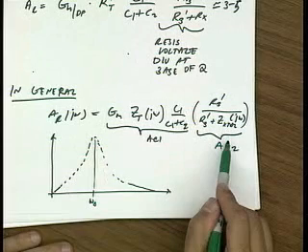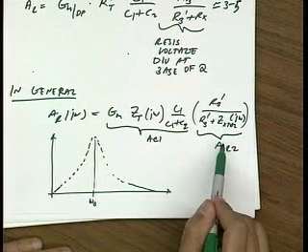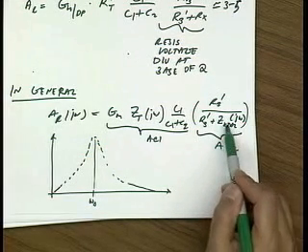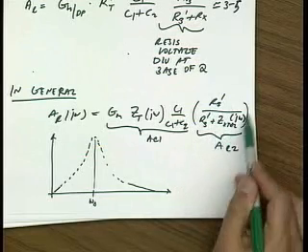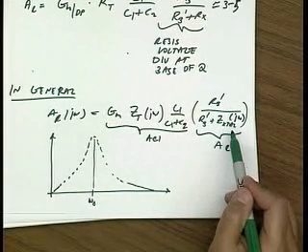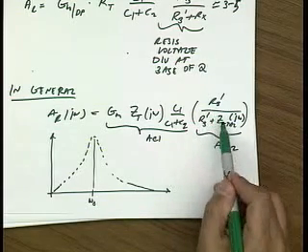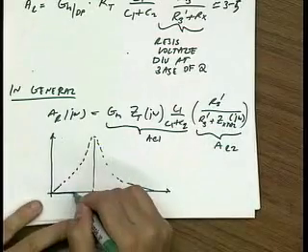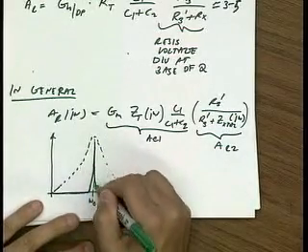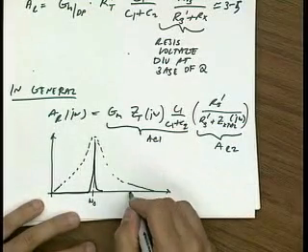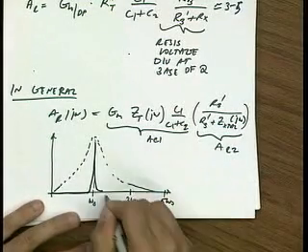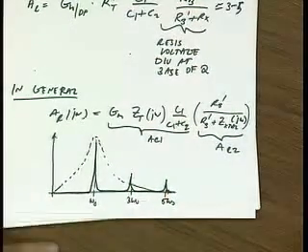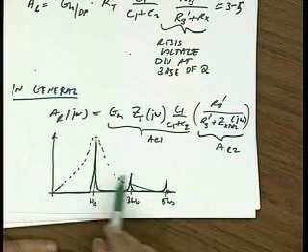If I look, on the other hand, at AL2, it's basically at resonance, let's say at omega naught, this is just Rx, and you get basically some divider, let's say 1/2. As you move away from resonance, though, this turns into a large impedance, and this gets very small. And you don't have to move very far away for that to happen. So if you actually do a plot, you see that it's a very sharp resonance. And likewise, at 3 omega naught and 5 omega naught, you see a very sharp resonance. And so this is very frequency selective.